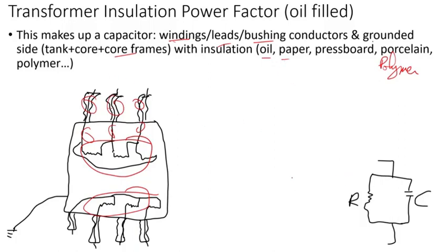Again, if you go back to the model, when you apply voltage, it's an AC voltage, and that voltage will depend on the withstand of the system you are testing. For large transformers, typically 10 kilovolt (kV) AC voltage is applied. However, if the windings you are energizing are rated 480 volts, for instance, you cannot apply that. You have to be careful not to exceed the withstand of the windings. But for large transformers, 10 kV is typically applied.